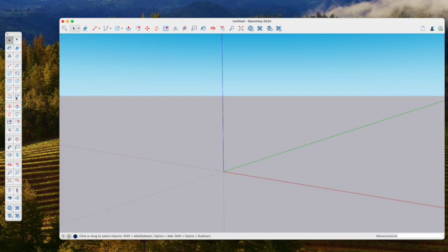First thing we're going to do is just draw a rectangle. The whole goal of this is I'm going to show you how to do the basics of making copies, the basics for using SketchUp, using references, etc. So anyway, here we've chosen the rectangle tool. I'm going to drag it out. All right. And then we're going to use the pull tool to make it into a 3D shape.